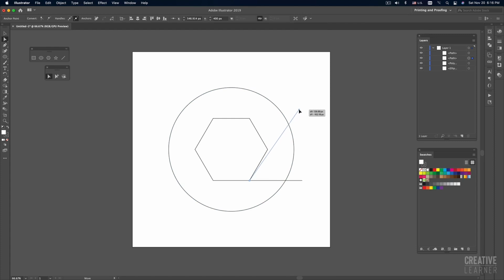After that, you can slowly snap it, and when we see this pink Smart Guide line, that is exactly making a straight line from the polygon side. So now we are sure that we have this one more side like that. After that, same thing, using the direct selection tool, Command C, Command F, I will do it quickly. Now we have this pasted in front.